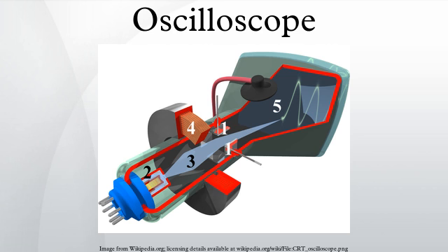In addition to the basic instrument, most oscilloscopes are supplied with a probe as shown. The probe will connect to any input on the instrument and typically has a resistor of 10 times the oscilloscope's input impedance. This results in a 0.1 (10X) attenuation factor, but helps to isolate the capacitive load presented by the probe cable from the signal being measured. Some probes have a switch allowing the operator to bypass the resistor when appropriate.